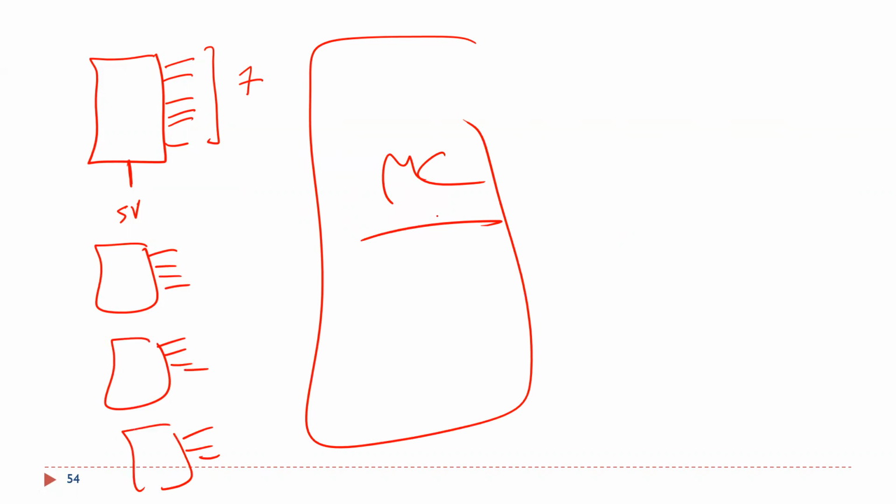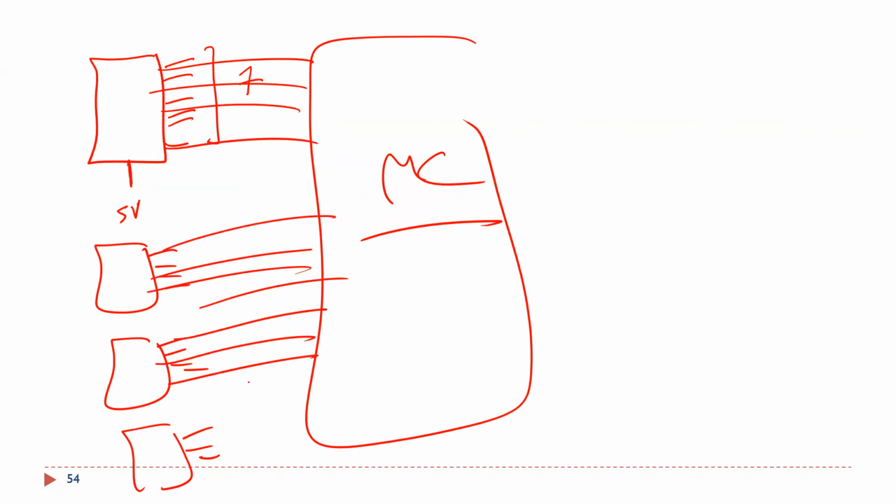Look, how many pins do I need? Too many, right? Because I'm going to connect 7 here, 7 here, 7, 7 this way. So it's going to be 7 times 4, which is actually 28. The whole processor has, I think, 30 or 32 pins, so just for that it's too much. You understand the problem? We don't have enough pins to connect it this way. So what can we do? How can we reduce the number of pins?